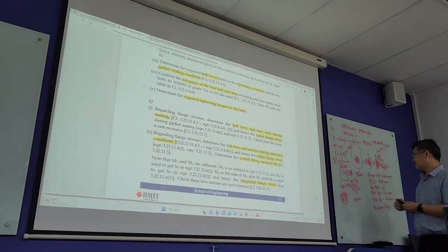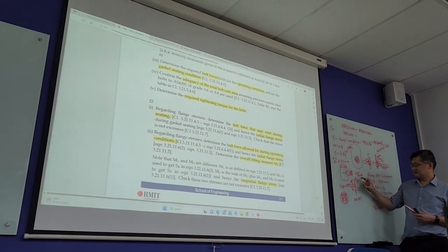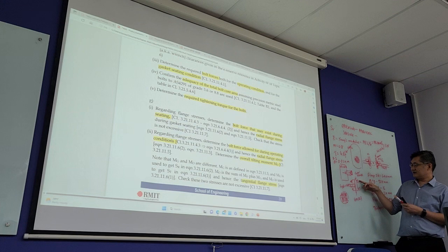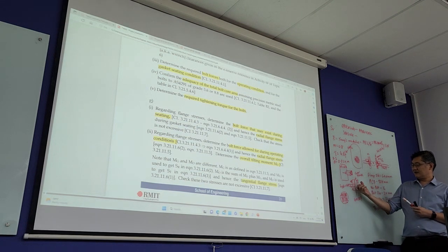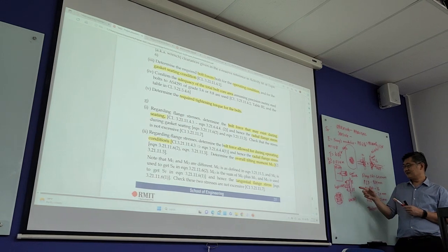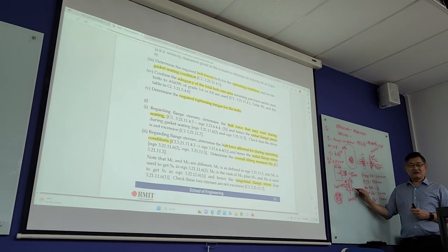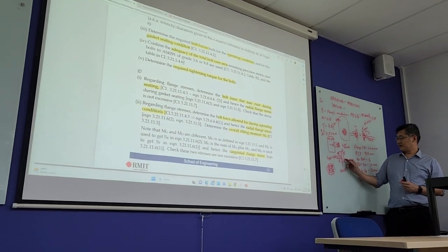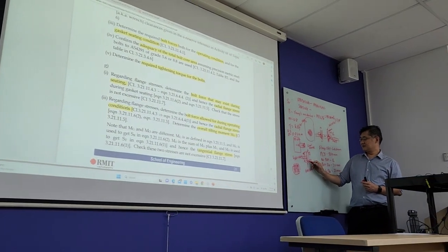So what happens is this. If, let's say, this is your flange cover, the bolt secures it. If let's say there is pressure coming out from this vessel itself, and you don't tighten this properly, say this one is loosening, you will have pressure in here.